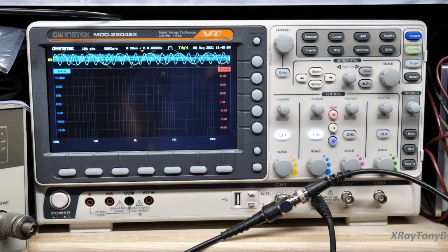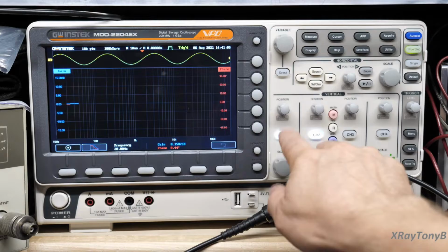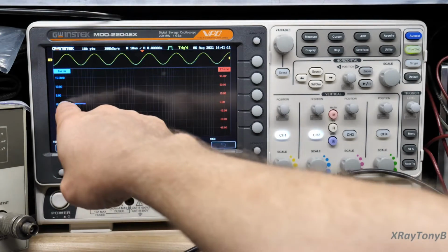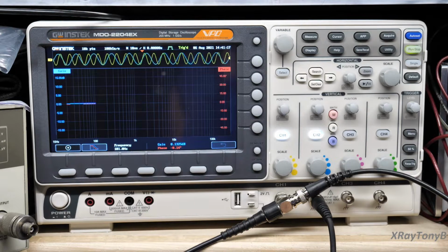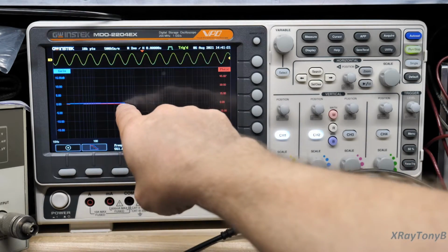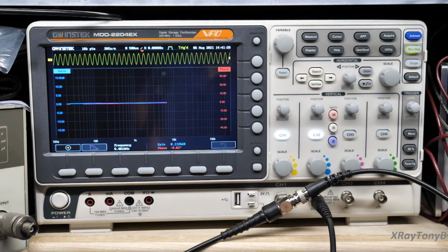FRA run, and we'll talk more about the setup here in a minute, you can see it goes through its self-calibration process where it sets the scaling of the two channels. Then it starts sweeping the signal from 10 hertz all the way up to 30 kilohertz. That's what I have it set to right now. I'll show you how to do that in a minute. And what it does is it puts out the frequencies, then it reads them back, and then it displays it on the plot there. And this is your Bode plot.